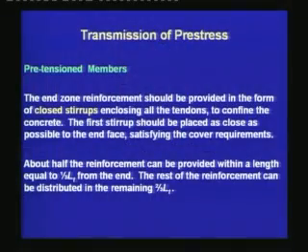The end zone reinforcement should be provided in the form of closed stirrups enclosing all the tendons to confine the concrete. The first stirrup should be placed as close as possible to the end, satisfying the cover requirements.